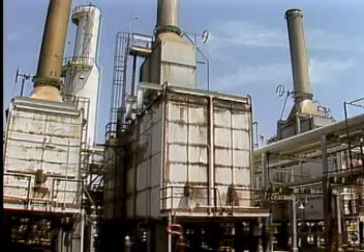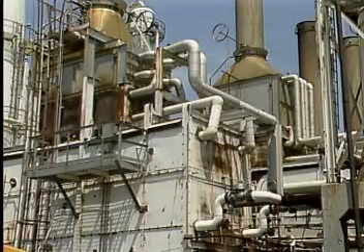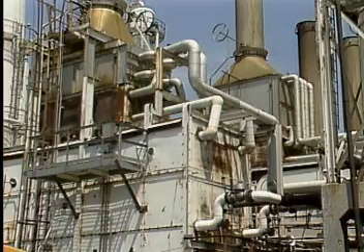Now let's say the heat from combustion is used to heat a process fluid flowing inside furnace tubes. Much of this heat from combustion, or thermal energy, is transferred to the process fluid. Since no furnace operates at 100% efficiency, not all of the heat is transferred to the process fluid. Some of it may go up the stack. Some of it may be absorbed by furnace equipment, but all of it goes somewhere. That is, all of the thermal energy is accounted for, so none of it is destroyed.